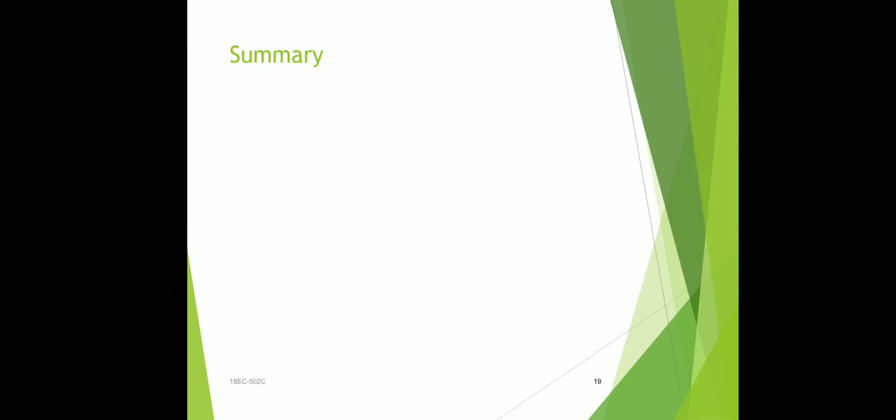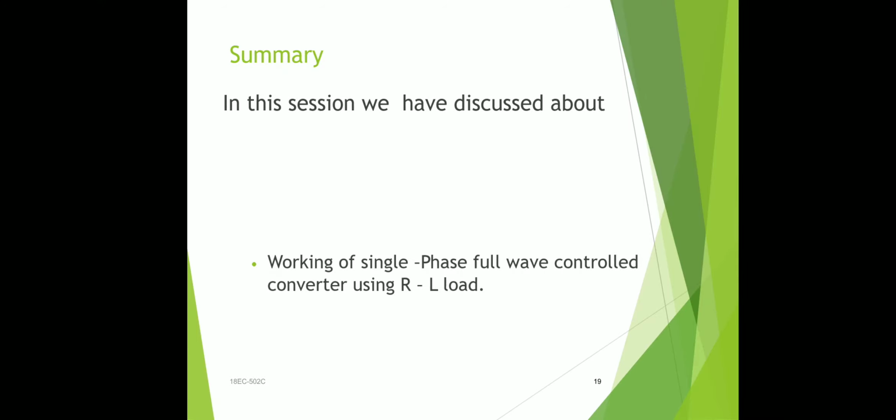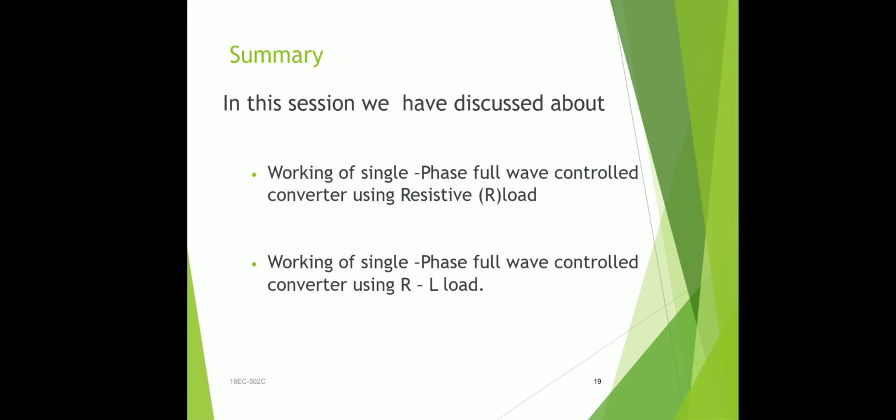This single phase fully controlled rectifier with resistive and RL loads: two circuits, R load and RL load. There is also another type using a freewheeling diode, and the input and output waveforms of each circuit we discussed.